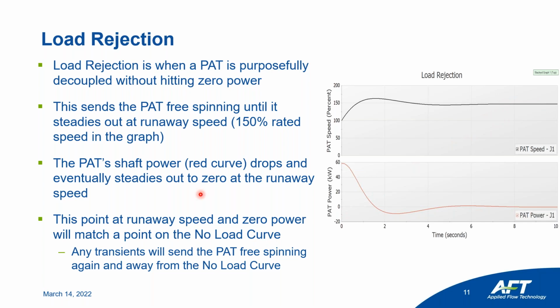So this point at the runaway speed and zero power will match a point on the no-load curve. So when you see where the pressure and the flow has steadied out at this point of time, that point of head loss and flow through the PAT would match a point on the no-load curve.